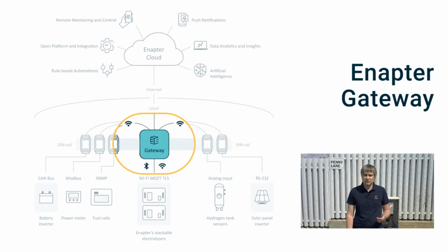Or making simple time-based rule to charge batteries only from solar during daytime will help to ensure we don't use expensive grid energy for this purpose. With such approach, we can set up any logic, from simple to very complex. In case if standard conditions are not enough, integrators are more than welcome to set up more complex logic using Lua customization toolkit and command line interface of our gateway.